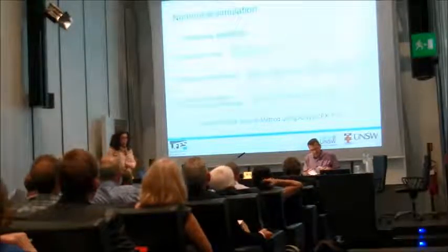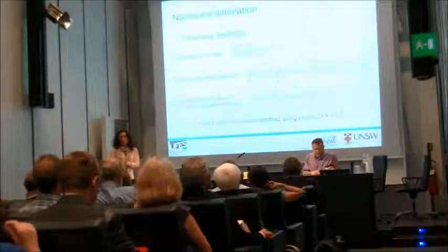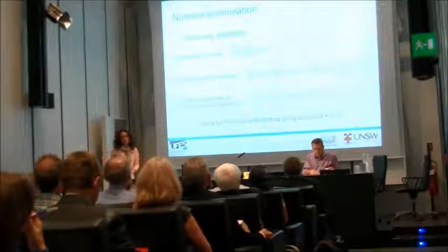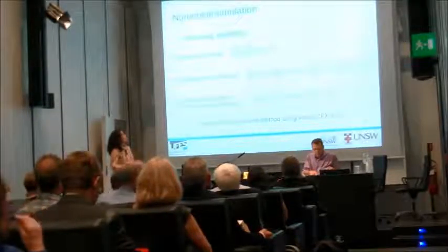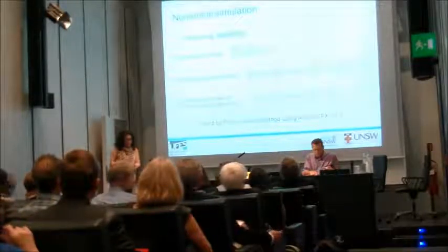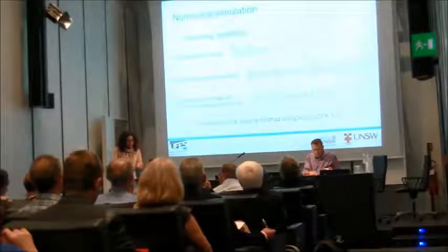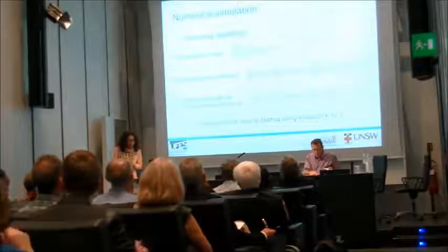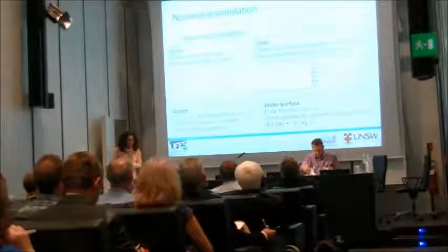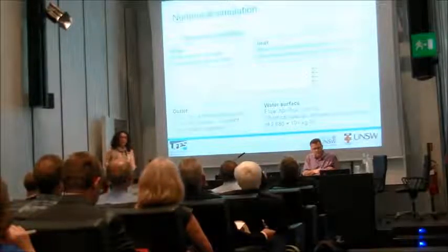To simulate the flow using CFD, we have to solve these straightforward equations: continuity, conservation of momentum, and the mass conservation of the chemical species we are interested in. We use the software ANSYS CFX 13. To solve those equations, of course, we need boundary conditions.